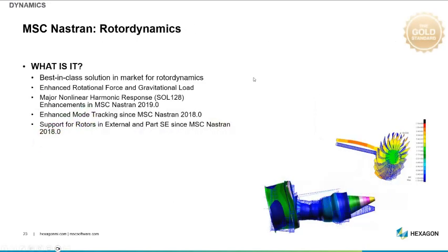Okay, then rotordynamics. When things spin, it's really easy for stuff to start going wrong. So your natural frequencies change as a function of the speed. And we get to the point where static loads start to excite a mode, something like this. So we've got a bearing with stiffness, that's why it moves up. As it's spinning, that load on the shaft is in different directions. So at some point, that static load of gravity is actually creating a load in different directions as this thing spins. But it's more complex. So there's the Coriolis forces and so on that's also taken into consideration.